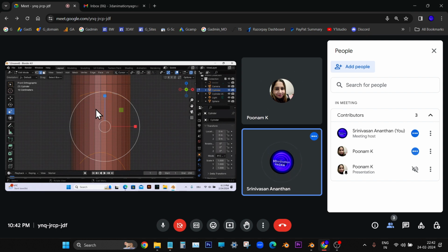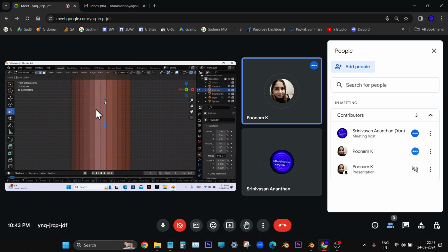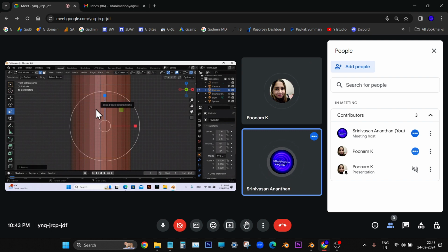Yeah, you have pressed the Z handle. Just drag the mouse downwards. Now type 0. Yeah, that's all. Now escape. This is called special manipulation. Only in Blender can we see this option. Without going into any transform XYZ location or rotation values, we can rotate using this special manipulation.